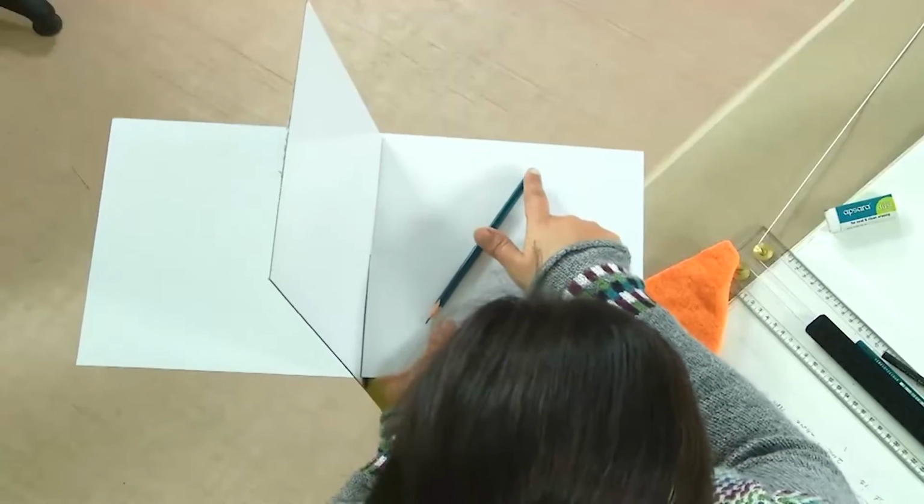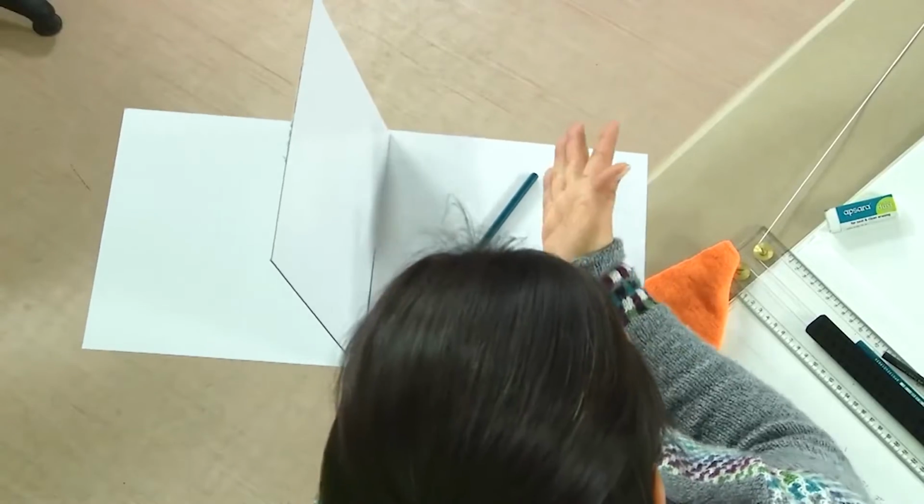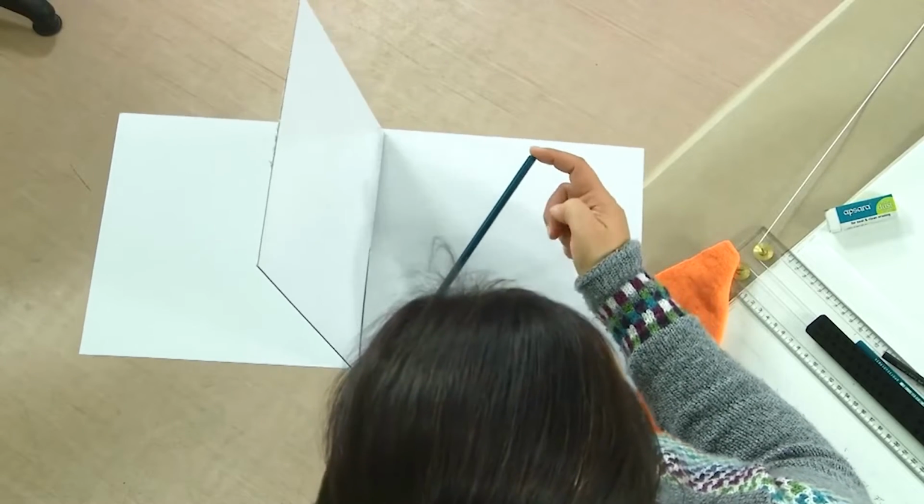We can understand it in the reverse manner as well. Imagine that this line is parallel to HP and it is making an angle of say 30 degrees with VP, which is the final angle. Now, we have to move this line in such a way that it additionally makes an angle of 45 degrees to HP as well. And how do we do that? In that case, we will not move it like this, but we will move it in such a manner that the distance this point has from the xy continues to remain the same. So, we move it like this.